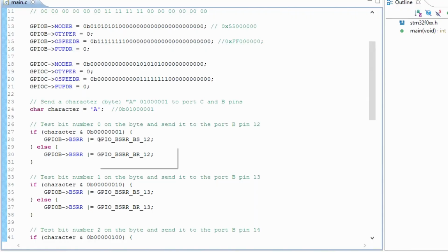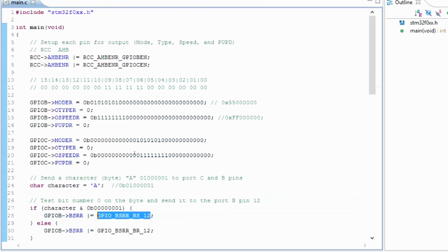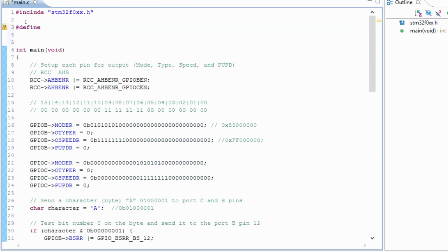First thing I'd like to do is create definitions for these bits. This will also help us understand how the circuit is connected with the microcontroller and the LCD. So which pins and ports go to which data pins, and the enable, read/write, and register select. So let's set up the defines up here. I want to create something very understandable in the way that we have the circuit wired, and that would be LCD D0 through D7 as my names for the defines.